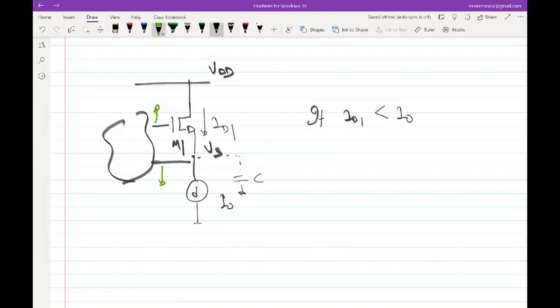Okay, I can do something with the resistor, that is fine. So how do I make that arrangement, right? If one side increases, the other side decreases. Yeah, a common source amplifier, right? 180-degree phase shift. If input increases, output decreases. So I can stick in a common source amplifier there. I haven't yet said that the relationship between Vs and Vg has to be equal to 1. It can be anything. We have to go and figure out what it is.